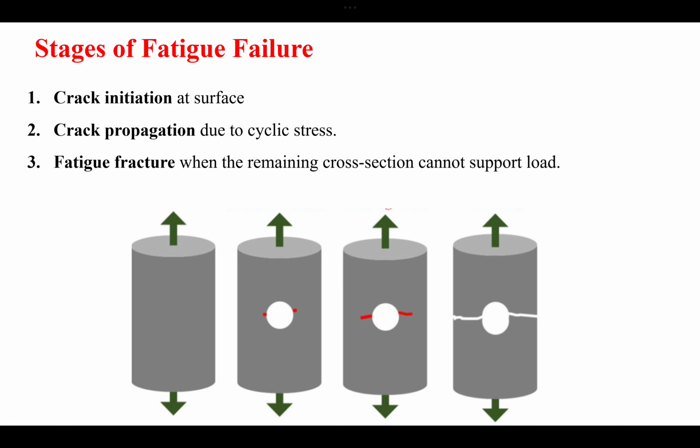When failure occurs due to these applied loadings, it occurs in 3 stages. Initially, cracks initiate at the surface. If you drill a hole in this and then apply some cyclic loading, it will start a crack. That is the initiation. Then you get the crack propagation.